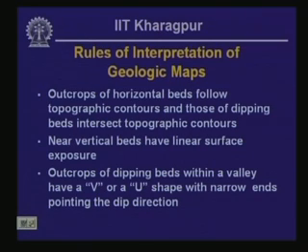Outcrops of horizontal beds follow topographic contours, and those of dipping beds intersect topographic contours. We are going to illustrate this one with a picture in one of the next slides. And secondly, near vertical beds have linear surface exposure.